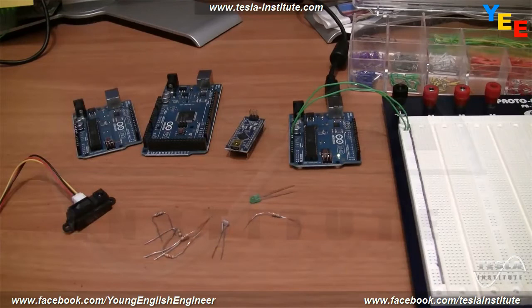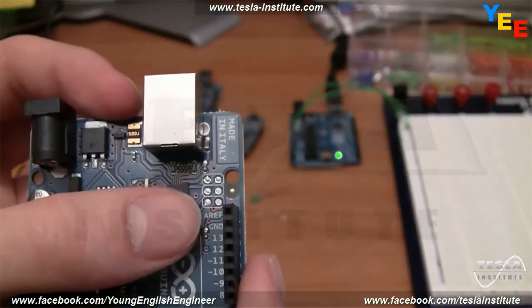You can set the reference voltage that you use for the analog inputs on all these Arduino boards. By default, it's set to 5 volts or 3.3 volts on 3.3 volt Arduino boards, but here we'll just be working with the default 5 volt boards. You can also set it to an internal 1.1 volt reference, although that's not available on the Mega. And on the Mega, you can use different commands, set it to 1.1 volts or 2.56 volts as a reference. You can also set your own voltage reference by setting it to an external value, which you input into an analog pin on the Arduino. Here we can see the analog reference pin that I was talking about.